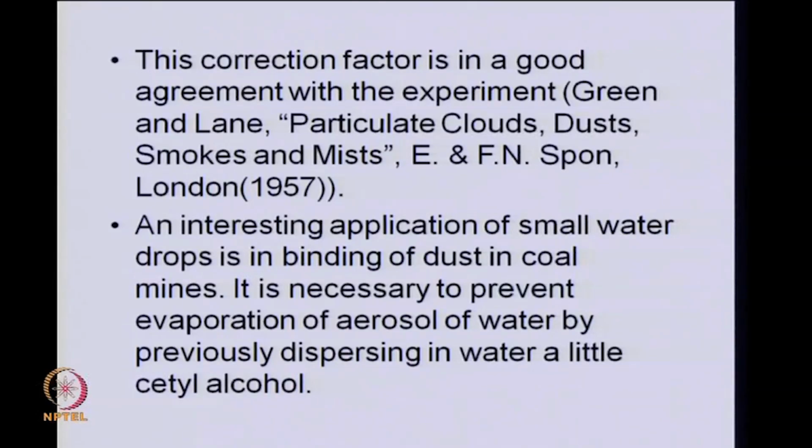You could do it by adding some monolayer forming materials. Once again the cetyl alcohol comes into the picture. Traces of cetyl alcohol previously dispersed in water will be able to prevent the evaporation of these aerosol droplets, and you would be able to bind the coal dust together.